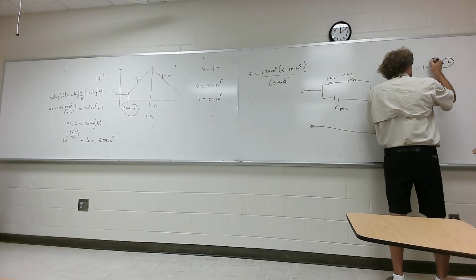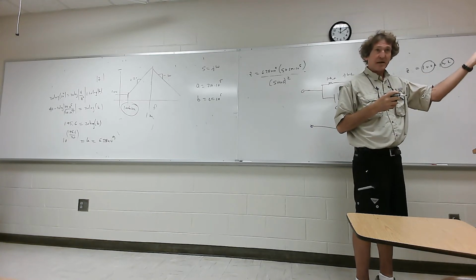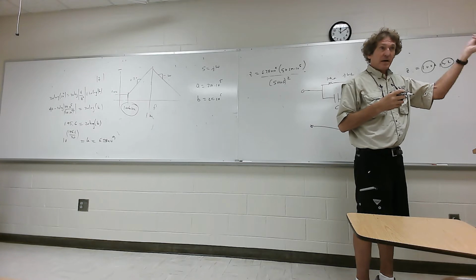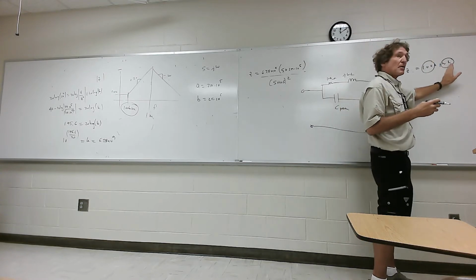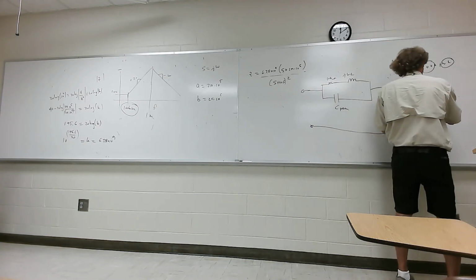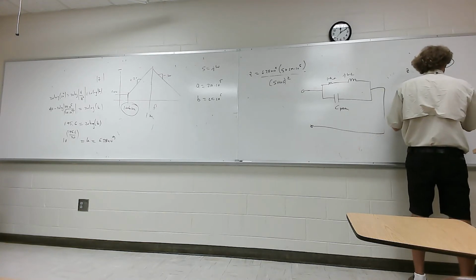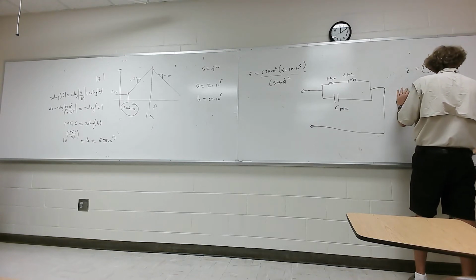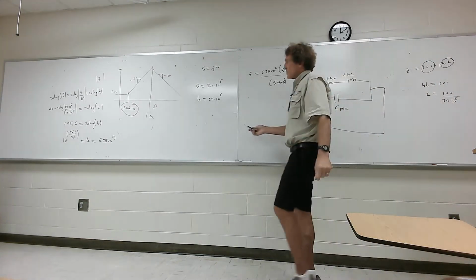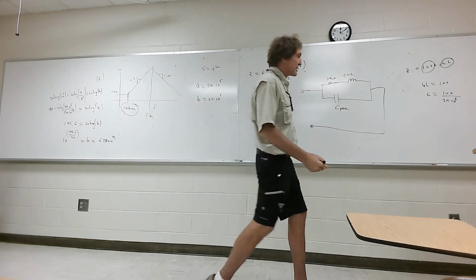When omega L is equal to 100, that's where the j omega effect starts taking over. Do y'all follow me on this, class? The way it'll always be, when the imaginary component is equal to the real component, at that frequency is when the pole or zero really kicks in. For this one, if omega L is equal to 100, then L is equal to 100 over omega, and omega is 2 pi times 10 to the 5th. So what's that value going to be? Anybody give that to me?